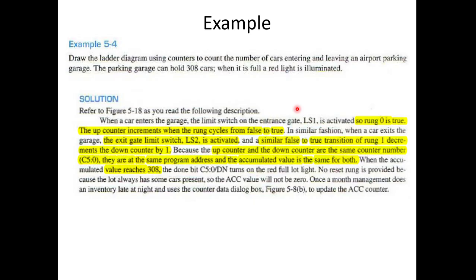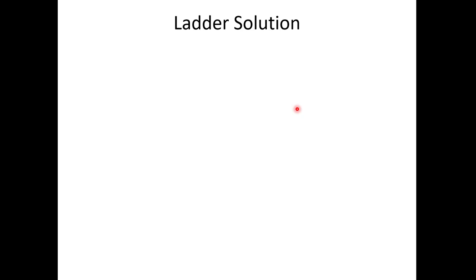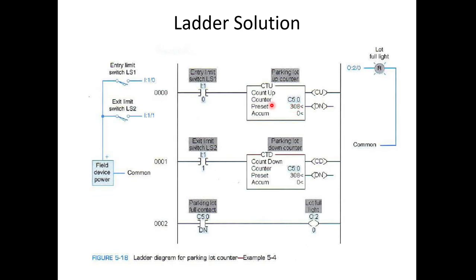Next slide. So this is the car park slot. Let me explain this. Basically, the entry gate detects the count up. Very important to note is that in both count up and count down, you have to have exactly the same counter address, because you are referring to the same memory, but you are using two sensors to detect it in two different ways. The entry sensor is detecting it as a count up counter. The exit sensor is detecting the same counter as countdown.